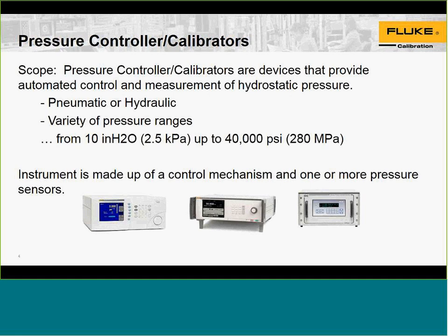And the last model in our family of pressure controllers is the one in the middle, the 6270A, which is a tubular pressure controller. It has interchangeable ranges, I think 42 ranges, from negative 100 kPa for negative gauge, all the way up to 20 MPa or 3,000 psi.